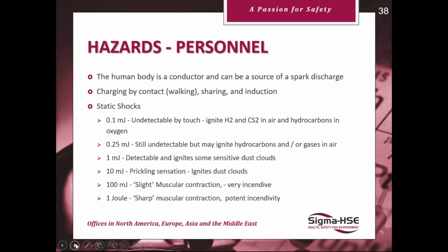One millijoule is detectable, like a feather brushing against your fingers, and can ignite some sensitive dust clouds. 10 millijoules is a prickling sensation, and you can ignite a lot of dust clouds. 100 millijoules is a slight muscular contraction, very incendive. 1 joule is very sharp muscular contractions, highly incendive.